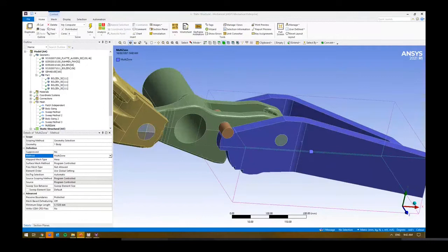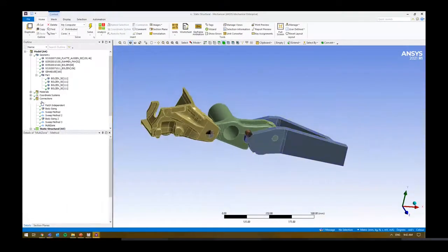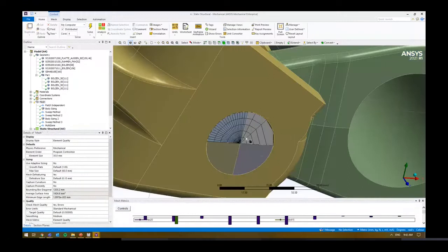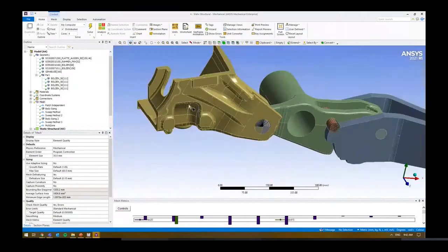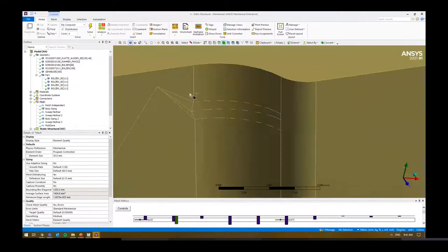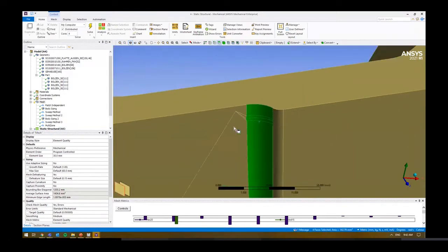As we're talking, we're going to go over questions, as a general rule, for what's considered appropriate sizing. Appropriate sizing, I'd look at this and ask yourselves, what do you want to actually capture, right? And that's what's going to tell you what the appropriate sizing is, right? If I've got a fine curve around here I want to capture, I want a couple of elements, right? Sometimes 3 elements across that feature, right? Across that, say, surface, in order to capture what's happening around that region.